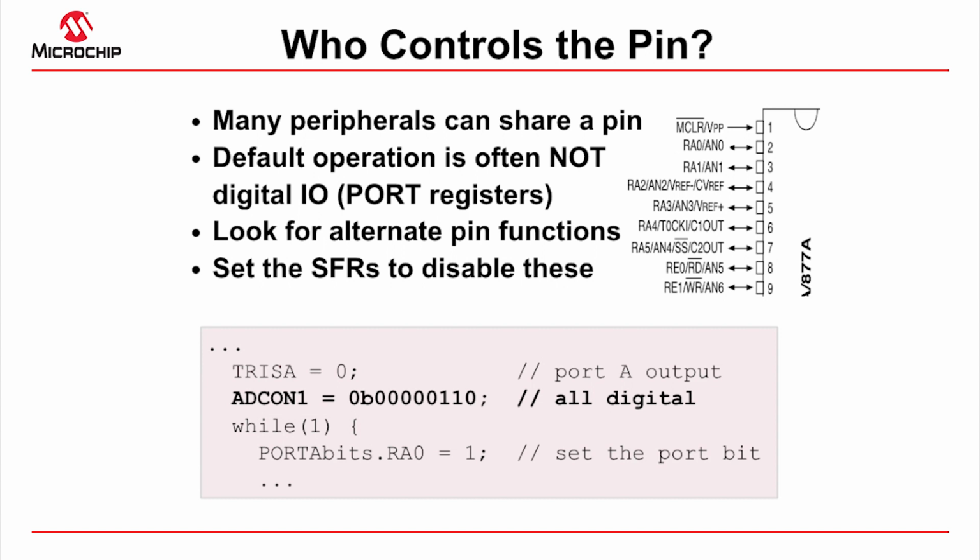Well, that won't be useful if we are trying to flash an LED, so in our example we have added code that will configure the port pins to be digital I/O. This is shown in bold type. The changes we have made to our example code so far will solve most problems, but there are several other issues that affect simple test programs such as we have.